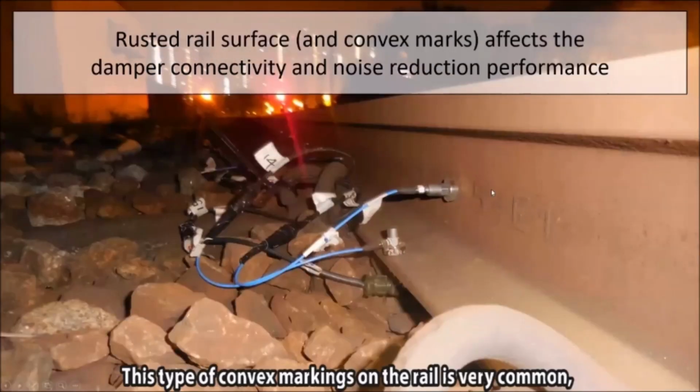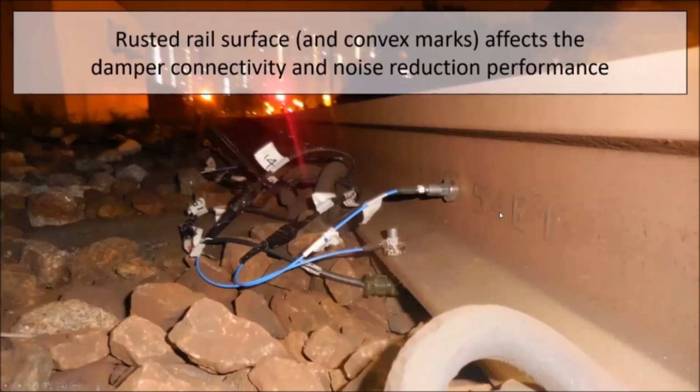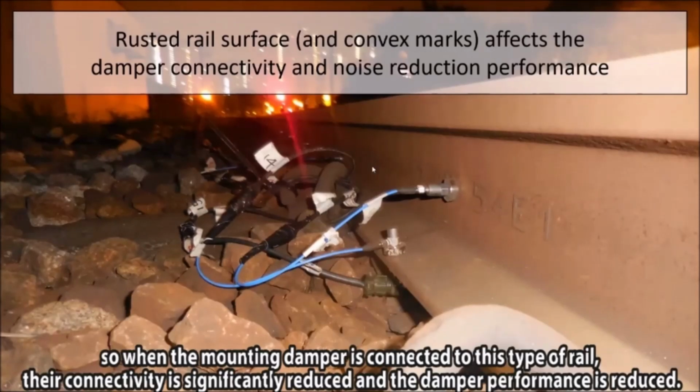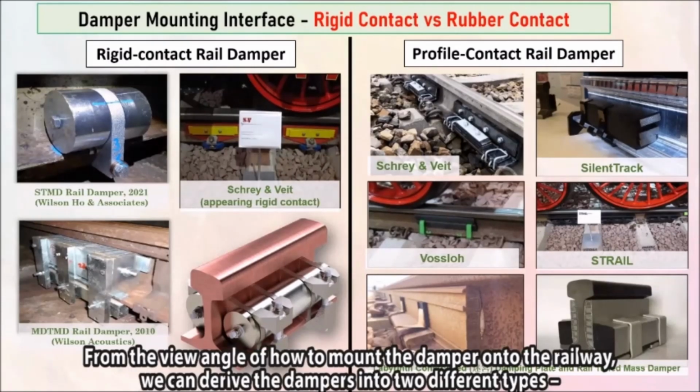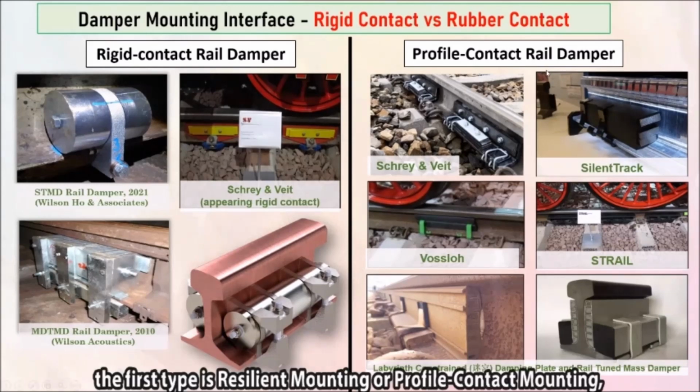This type of convex marking on the wheel is very common. So when mounting the damper on this type of wheel, the conductivity is significantly reduced and the damper performance is reduced. From the angle of how to mount the damper on the railway wheel, we can divide the dampers into 2 different types. The first type is resilient mounting or profile contact mounting.